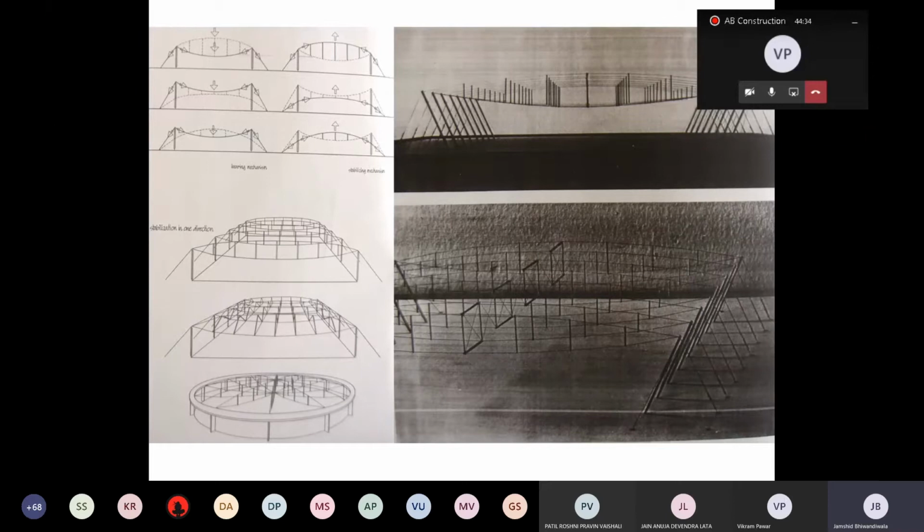Here, because they are cables, you can afford to have the top boom and the bottom boom be very lightweight, stretched across, with vertical supports to help the compression. So in some sense you are creating a bowstring truss. This is nothing but a bowstring truss created by heavy compressive members and lightweight tension members.